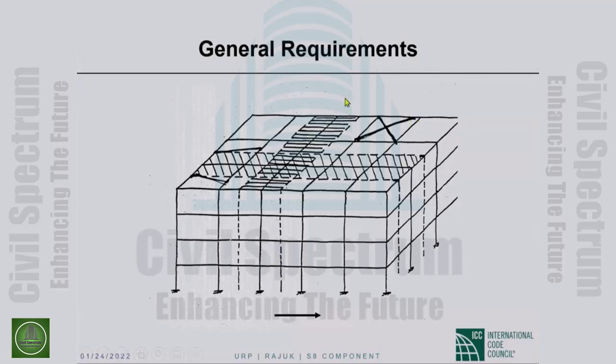And then we design the slabs by cutting those portions out of our structure separately in two orthogonal directions. So we cut this portion out of the structure, take it out, for design of the slabs that you see shaded.